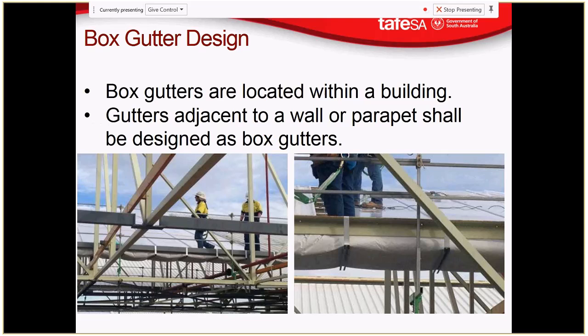One way you could help take the load off this gutter is to have more downpipes. So we have the plan view of our house here. We've got our gutter running all the way along there. Initially we may have had a downpipe there and a downpipe there. We add our veranda on here, which also gives a lot more roof area. We may be able to get away with putting a downpipe there and keeping the same gutter. But if we've got a window or a door here, or something like that, and for some reason we can't get a downpipe in a decent position, we might go for something like that. Or we can actually change that gutter and put in a larger gutter with a larger cross-sectional area.